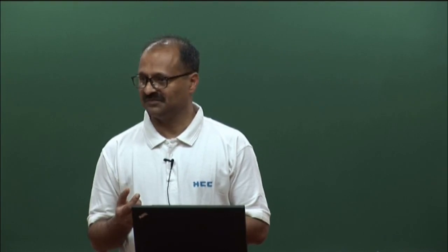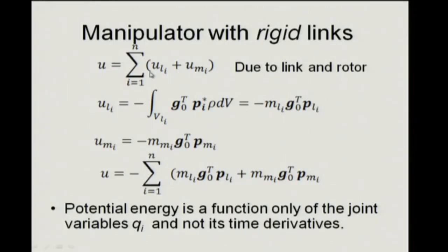Now if it is a flexible body, then that goes away, and the kinetic energy becomes a more complicated term because the body is reconfiguring itself. So you have to find out, and in doing this the moment of inertia will change as a function of time, even in the local frame. Currently we account for the fact that the moment of inertia is changing in the global frame, but at least in a local frame it is constant. After that we just need a rotation matrix, which you are experts at already, to take care of it. So we do not have so much of a problem. In the first cut we look at rigid links, but it is also interesting to know what deviations will come around when you are doing flexible.